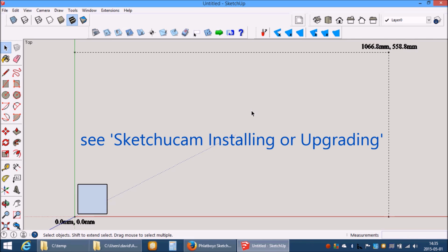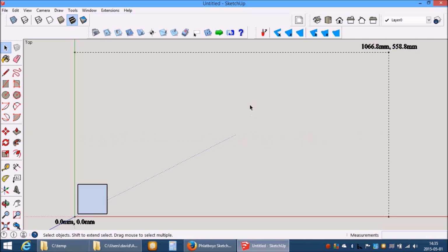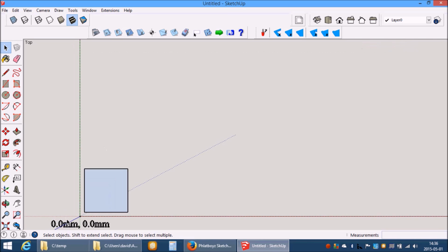As in the previous segment of video, you will have seen that you should set that to your router's maximum cut size. Note I say router as a generic term for a 3-axis milling device. You can use this with a Bridgeport or a Mazak or a Haas or an OpenBuilds Ox or a Shapeoko 2, 3 and whatever comes in the future, and so on. The software is written very generically so that it uses no fancy Gcodes whatsoever and will work on Grbl and TinyG as well as Linux CNC and Mach 3.